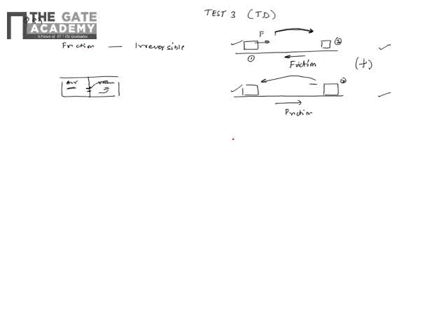Heat transfer across a finite temperature difference: it can be shown that when you transfer heat from a high temperature body to a low temperature body, this heat transfer is basically irreversible. It cannot be reversed, because if you want to reverse it, you need a refrigerator, which requires work to be done.